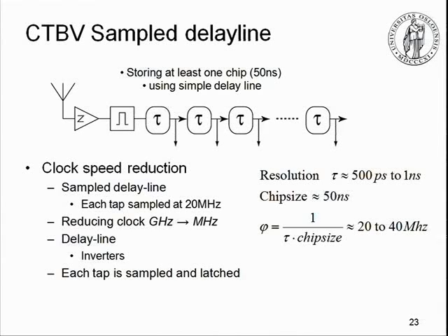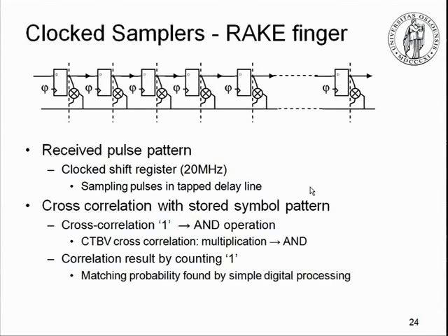It's a low clock. So now we can look at the history here by looking at these taps of the delay line. By reading out these taps, we know the history of my signal. And if we sample those signals, those are zeros and ones. Now we are in the low frequency clock domain, meaning 20 to 50 megahertz. We are able to make a sequence of ones and zeros, which is actually the one bit sequence we want to recover for our symbol.